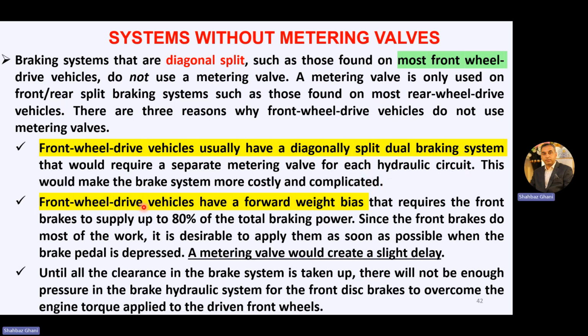Front-wheel drive vehicles have a forward weight bias that requires the front brakes to supply up to 80% of the total braking power. Since the front brakes do most of the work, it is desirable to apply them as soon as possible when the brake pedal is depressed.